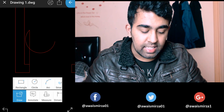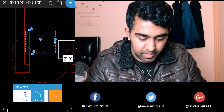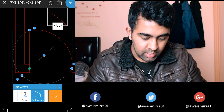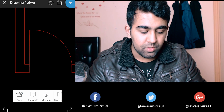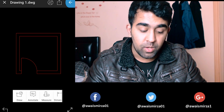So I'm going to select that arc now, and I'm going to edit the vertices. Okay, I'm going to select that vertex and I'm just going to drop it to this middle. Okay, I'm going to select this vertex and I'm just going to try dragging it about here. Alright, so I'm going to accept that. Alright, so we have done our door now. Let's go and make a window now.